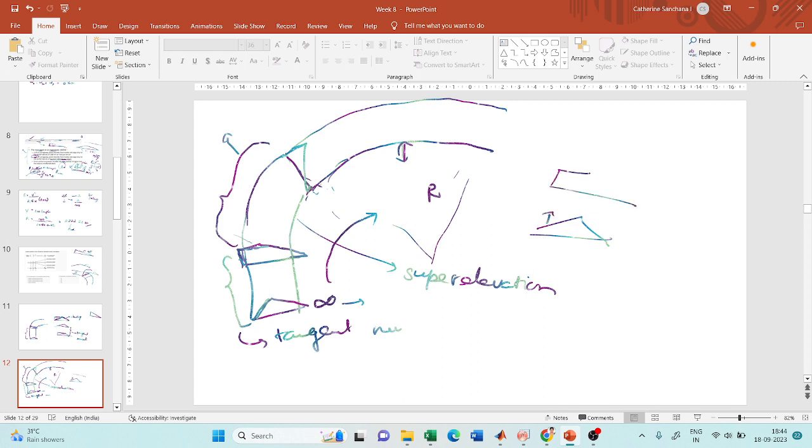to a zero slope. The slope is zero, right? And from this, it has to go up and become a triangle like this. So this distance, where you provide the transition from zero slope to a super elevated slope, is called the super elevation runoff. And this is where your transition curve will start, which means your transition curve will go only from this point to this point. This tangent runout, you will not include in the transition curve.